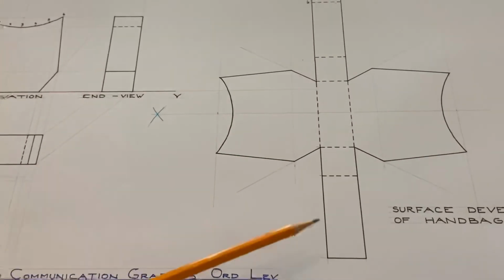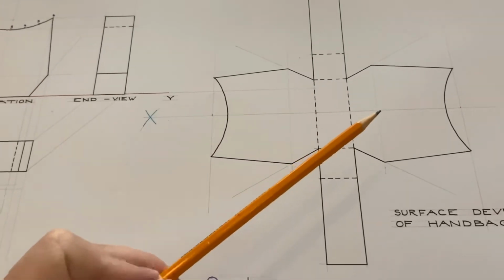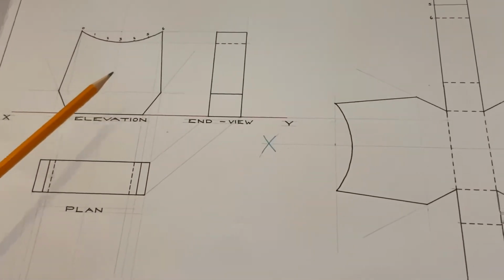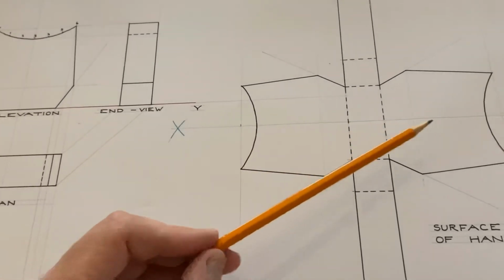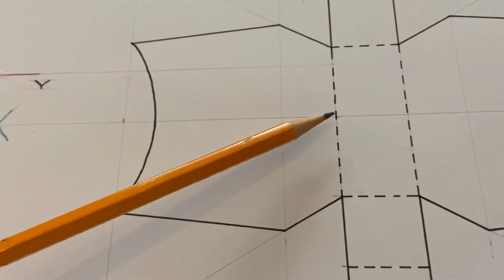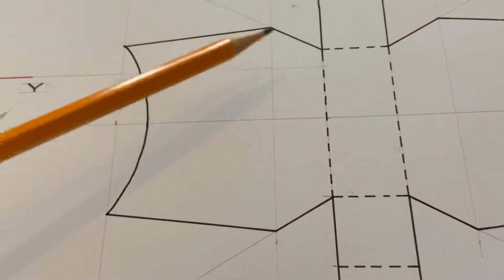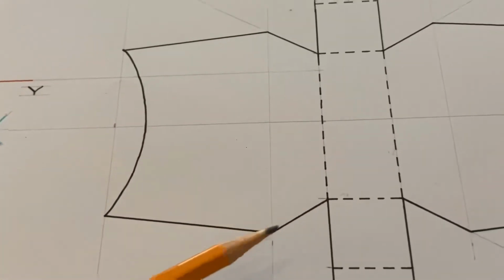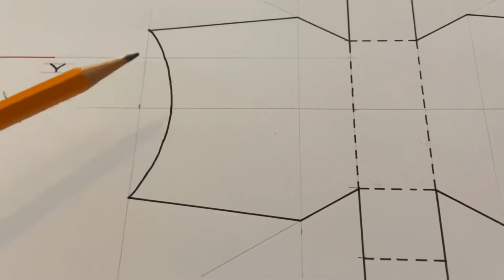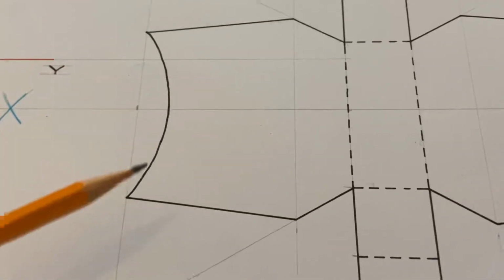So once you have the spine drawn, you want to get now the front surface and the back surface, and these are just 2 repetitions of the elevation. So what you have in elevation here, we have to attach that onto the development on both sides. So it's the same measurements that we used to set up the question. We measure out 20 to get this line here. This line is angled back at 60 degrees, and this line is also angled back at 60 degrees. Then from this line we measure up 80, and then to get those points out there, 70 in total. So from the center line out 35 and out 35.